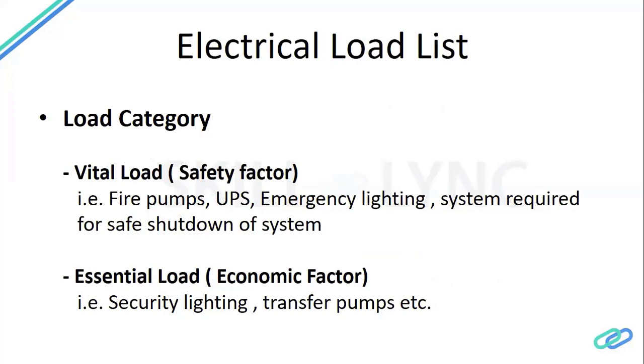If there is a fire in the plant, the fire pump should run anyway and the plant should be shut down safely. And if it happens in the night, the person should be able to evacuate from the plant, so they need lighting for that purpose. So these are the loads which are important for the safety of the plant.